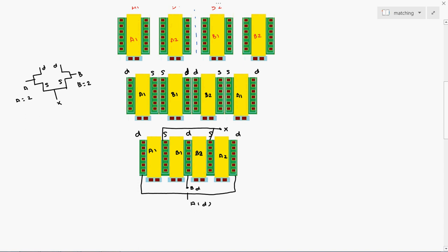As per my experience, this is not the best pattern in general. If there are shared source or drain nets, then we can go for this pattern. And one more thing, with A equal to 2 and B equal to 2, we do not only have the ABBA pattern, we have so many patterns. I will draw them.